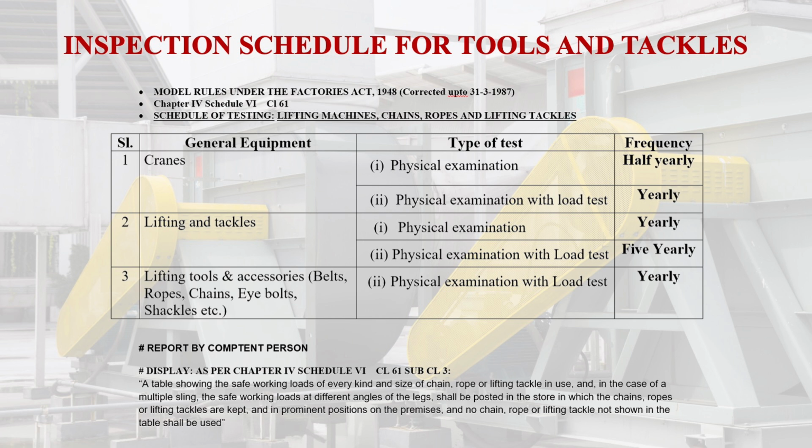The physical examination with load test is to be completed yearly. However, whenever you are using these tools and tackles, before the use of these, at least whatever inspections are possible you should carry out, so that you will have confidence that whatever tools and tackles you are using will not fail to perform in between the operations.